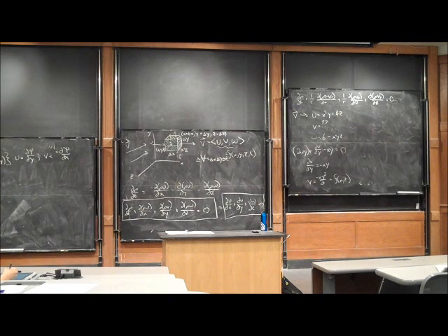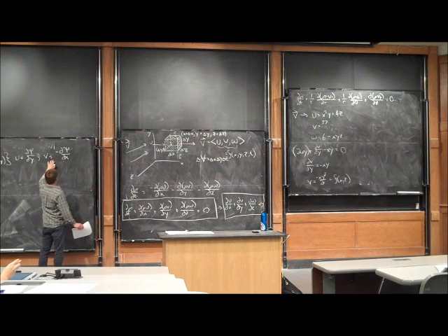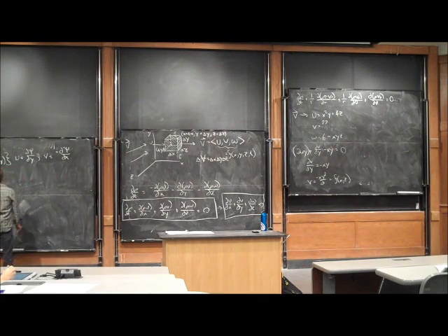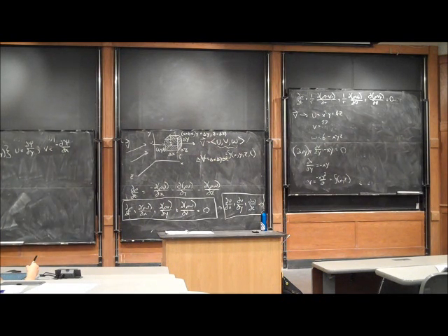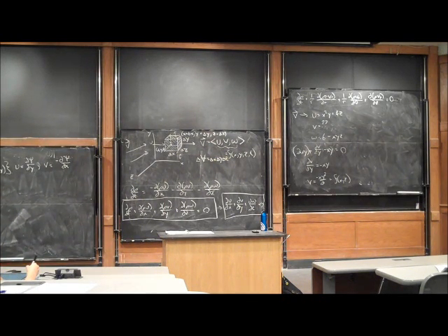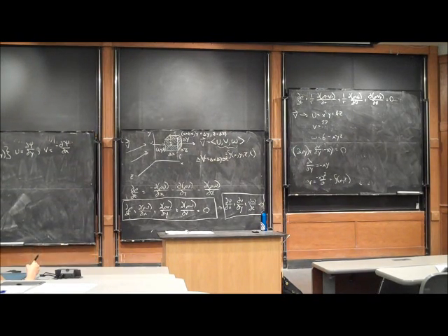But what I can then do is integrate u with respect to y and v with respect to x to find out what psi is. So this does several kind of important things. First, it reduces our number of unknowns from 2, in this case u and v, which we don't know, to 1. Now we only have one function of x and y that we don't know. But it does turn our conservation of mass equation from a first-order equation to a second-order equation. So it does have some ramifications to it.